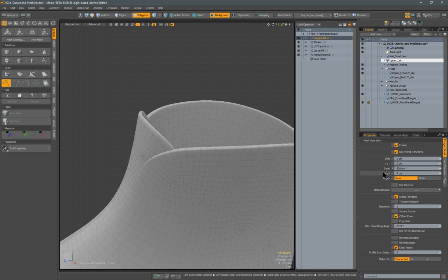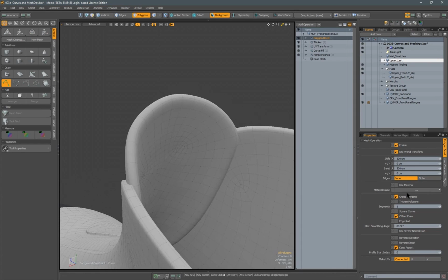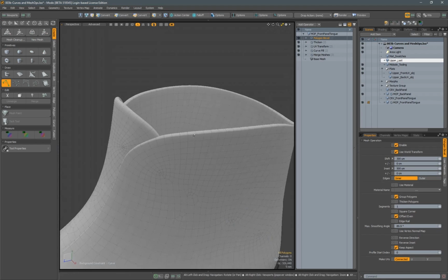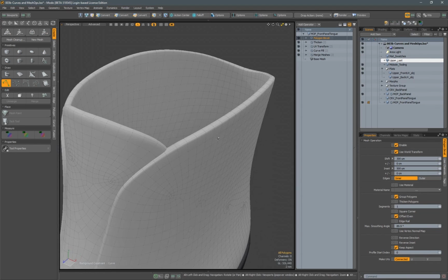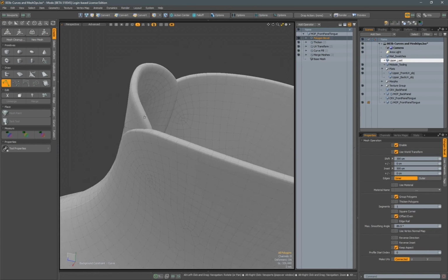We'll go negative 0.05 and negative 0.03 on those functions. And what we still need to do inside that poly bevel, just like the previous panel, is we want to specify those border polygons, or that poly loop that was created from the thicken function.